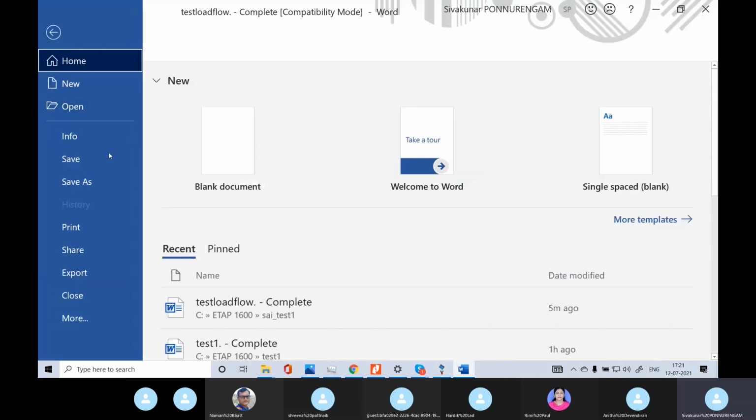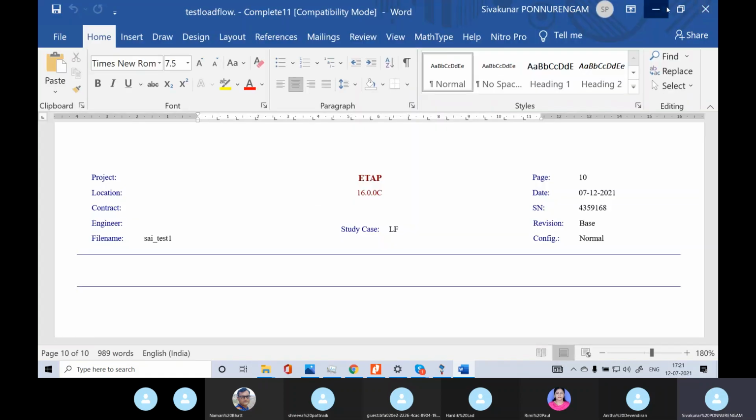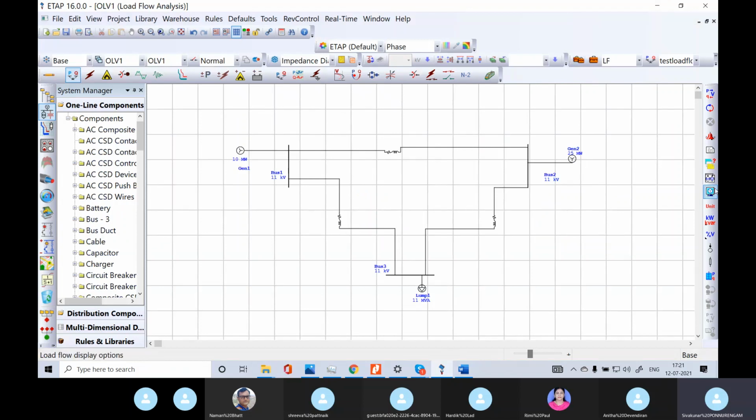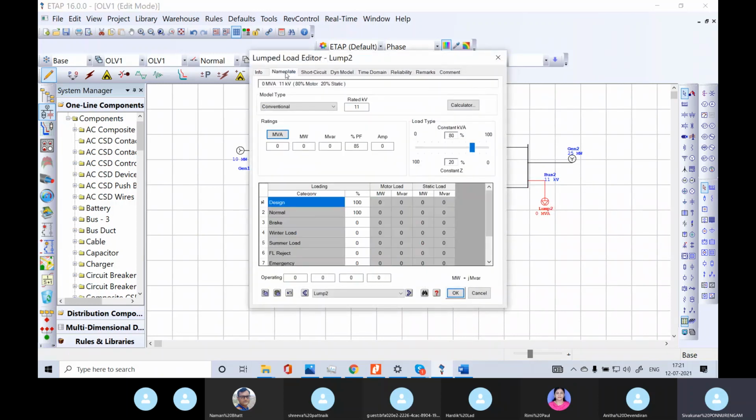Now I am going to change this for display purposes. So this is not visualized otherwise. So simply that is the negative and capacitive action. I am going to edit mode. So simply I am going to take another load. So this load is connected here, right? Connected to here. I am also going to take this load as 2 MVA, with a very low power factor of 0.6.